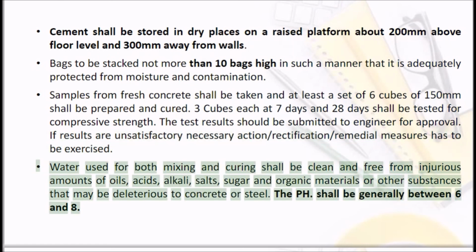Water used for both mixing and curing shall be clean and free from injurious amounts of oils, acids, alkali, salts, sugar and organic materials or other substances that may be deleterious to concrete or steel. The pH shall be generally between 6 and 8.